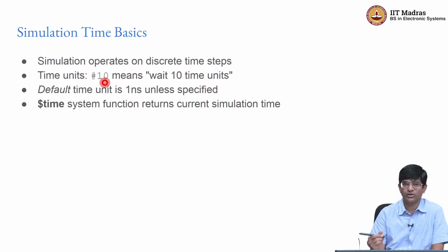You never have the idea of waiting at a particular point in the program, right? There are certain programming languages where, for example, you could think of the yield operation in Python as being vaguely similar at some level, right? It has this notion of waiting for something else to happen, giving up control, and then coming back at a later point in time. It's similar, not exactly the same. Verilog and VHDL have an explicit notion of time associated with them, which is not generally modeled in other programming languages.